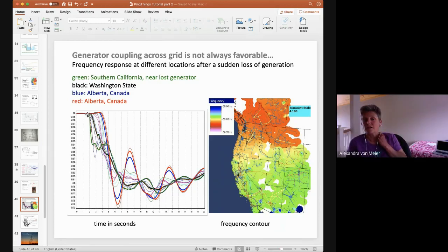Yes. So there's a thing called the ROCOF, which is the rate of change of frequency. But that really is mostly used in the context of a big disturbance. Like right here, you have a big bad ROCOF, right? Where over the time period of like 2 seconds, your frequency is dropping by a quarter hertz, which is a lot. I think what you're describing is more a metric of volatility. And I don't think there's a totally standardized metric of volatility.